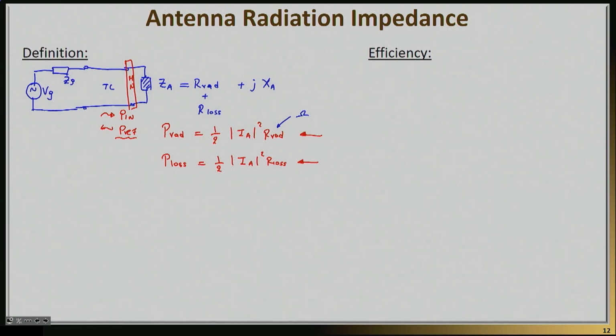to essentially minimize the power reflected by this antenna. So essentially, out of my incident power or my input power to the antenna, I have two potential losses, the reflected power and the lost ohmic power, and then I have one useful power that I'm basically trying to maximize. So based on that, I can also define the efficiency of an antenna, which we defined before.